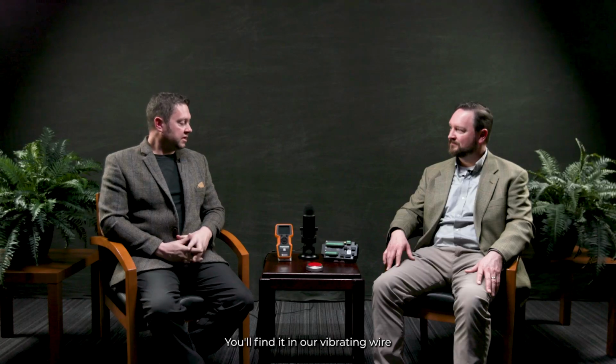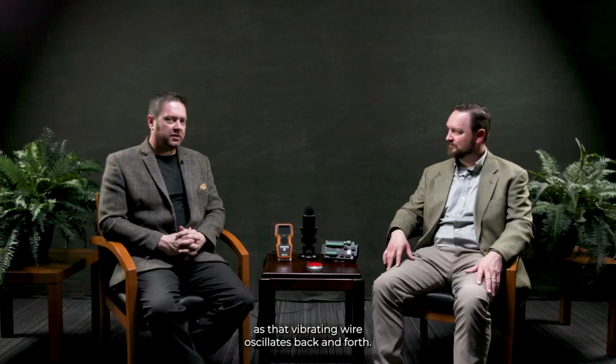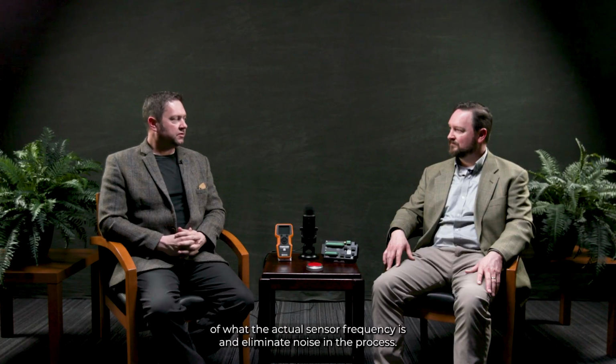Great, thank you. VSPECT is a patented measurement technology from Campbell Scientific. You'll find it in our vibrating wire data loggers like the CR6, the CRVW3, the AVW200, and our handheld field reader, the VW Analyzer. VSPECT is a time domain technology, which really means it measures the incoming signal as that vibrating wire oscillates back and forth. And then we perform some math on it, and we get a much clearer understanding of what the actual sensor frequency is and eliminate noise in the process.